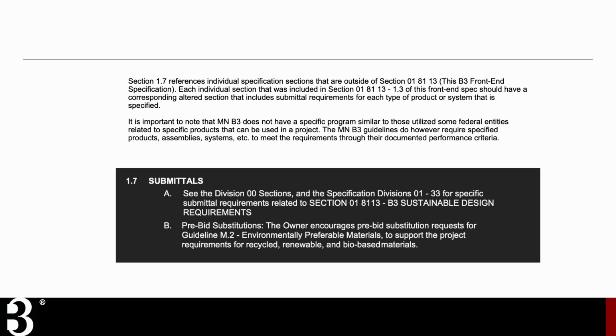The fact that the design intent is mainly represented through construction documents and through the spec manual, and submittals are how a contractor is to basically send a record of what they've chosen in terms of the manufacturer, the supplier, the specific variation of materials that are being proposed, and get that back to the design team to make sure that there's nothing that's been lost in translation.